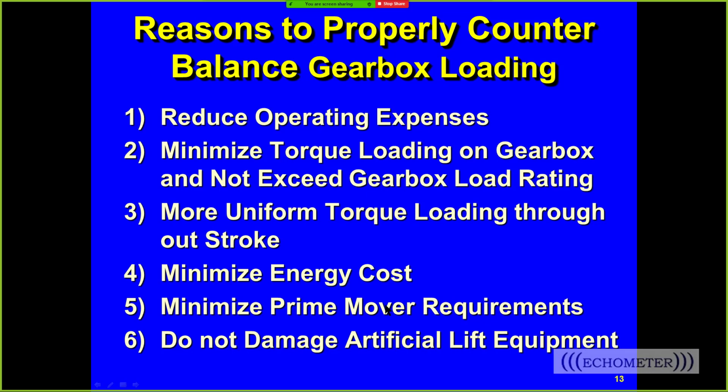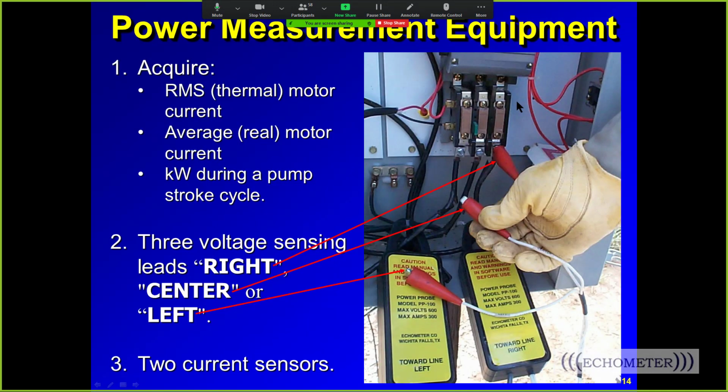So if you have higher torque loading, you'll need a bigger gearbox, or if you balance it, you may be able to use the existing gearbox on your well, and you'll prevent damage to your equipment. So those are some important reasons to be concerned about overloading your gearbox.